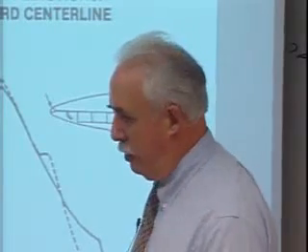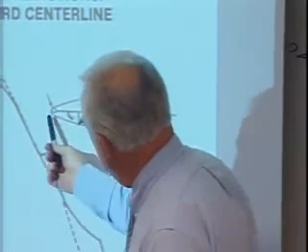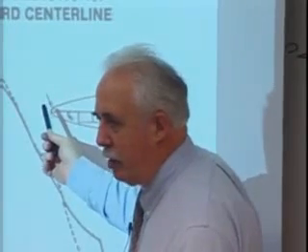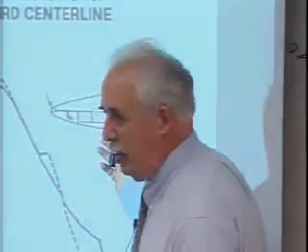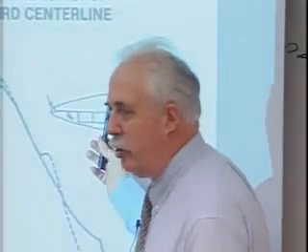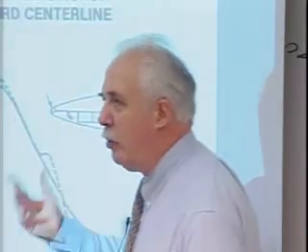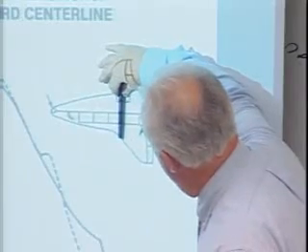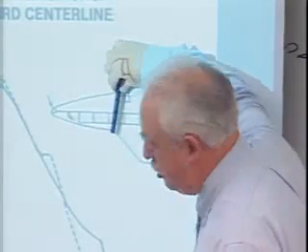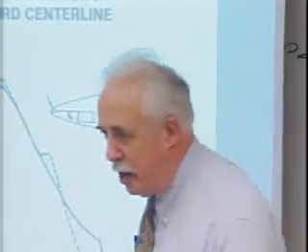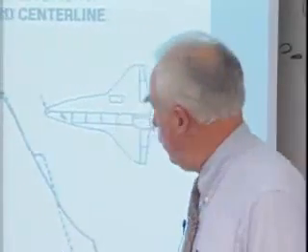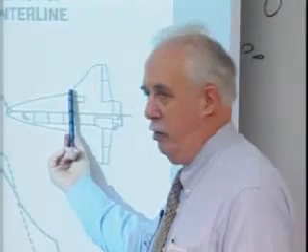Now, the flow field technology, we had a heck of a time getting from our starting solution, subsonic flow, which used one particular algorithm, to march supersonically down the vehicle. We succeeded in doing that prior to flying, and we were able to compute up to the point where the shocks from the wing intersect the shock from the fuselage, and then we had another subsonic region, and we weren't able to handle it. Now we can do that. But at the time we flew, we could only compute up to about here.